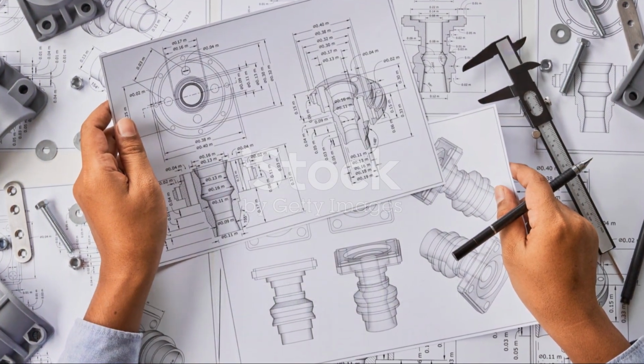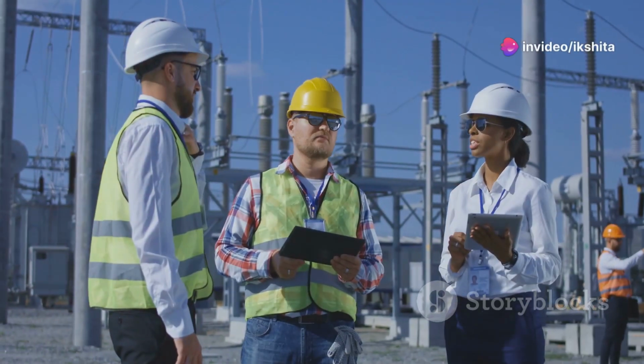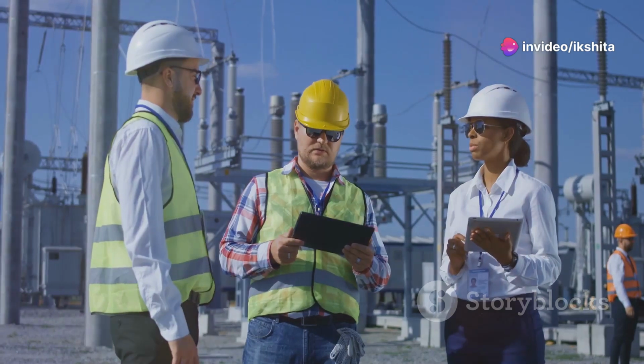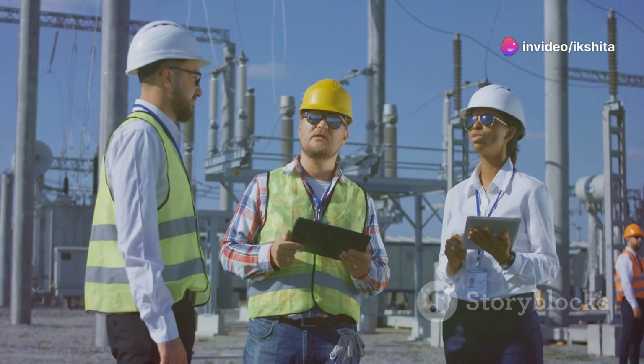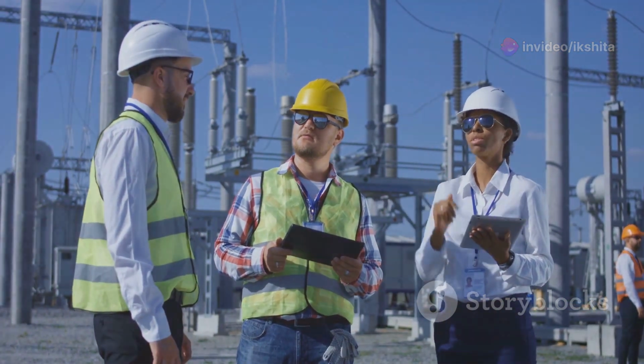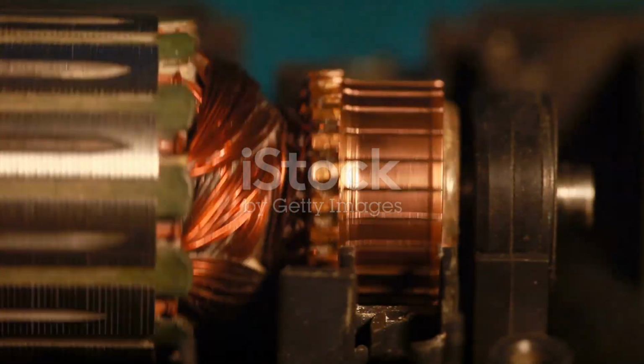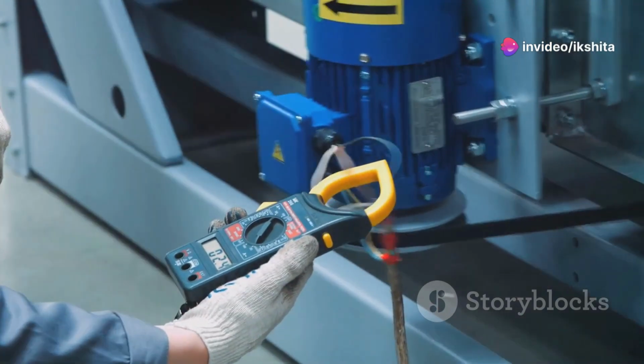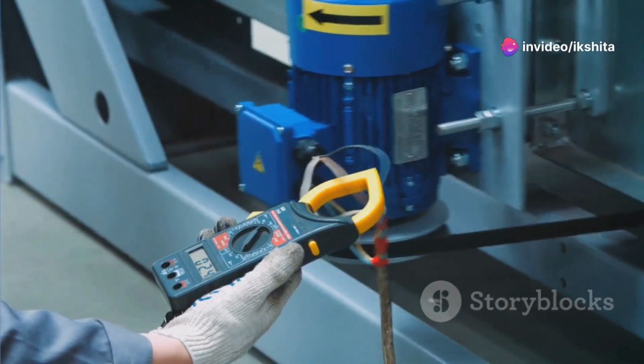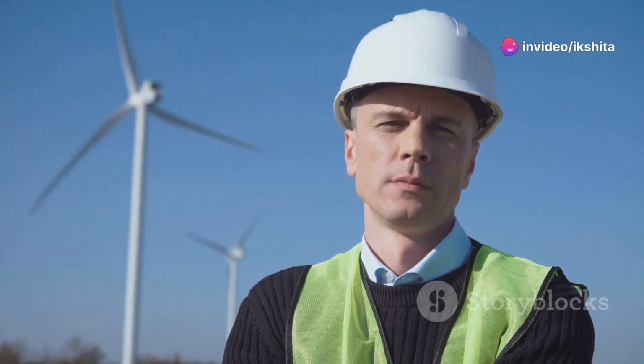Now, let's flip the script. A leading power factor occurs when the current leads the voltage, commonly seen in capacitive loads like capacitor banks and lightly loaded transmission lines. In this case, armature reaction has the opposite effect. It weakens the main magnetic field, reducing the machine's overall efficiency. It's like trying to run with a headwind, making it harder to achieve the same output.